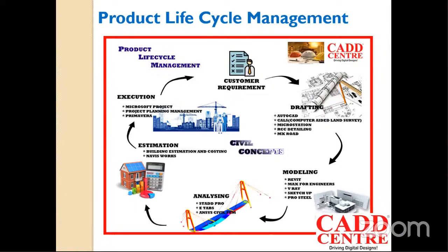So consider one room, and consider this as a classroom. What are all the needs in a classroom? We split the structural elements. What are all the structural elements in that? What are all the architectural elements? What are all the electrical elements? Consider this as a classroom or smart classroom. There are 6 columns in that. Structurally I'm drawing 6 columns, then 4 running beams, then 2 two-way slabs. These are all the structural elements present in that classroom. Then brickworks.